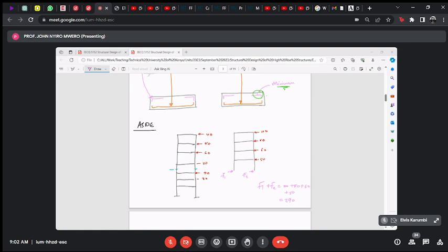It's because, yes, the shear does exist there, but the area that is carrying the shear is so big that nobody refuses you to check, but it's almost granted that you will not have a problem. The only problem you will have is if you have a concentrated load on a slab, then you check for punching shear. Similarly, this shear wall actually does carry axial load because there are slabs connected to it.